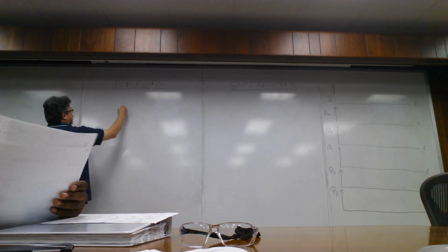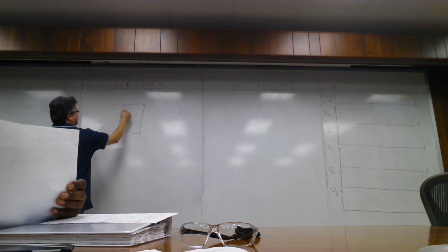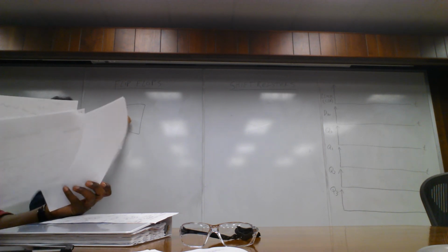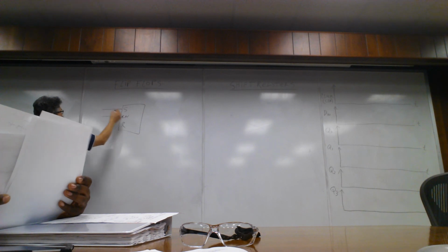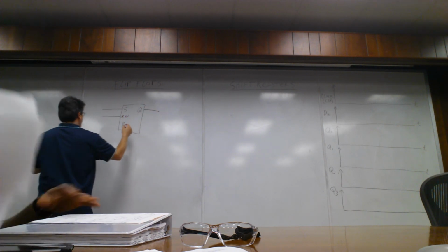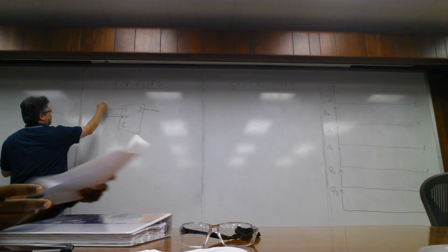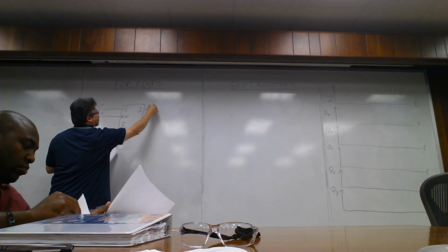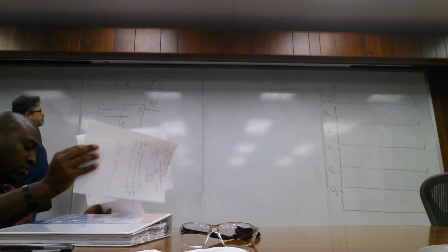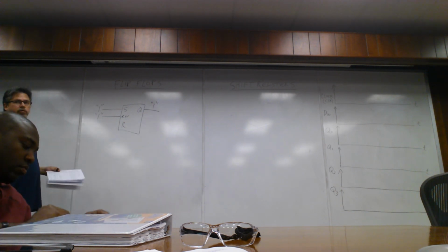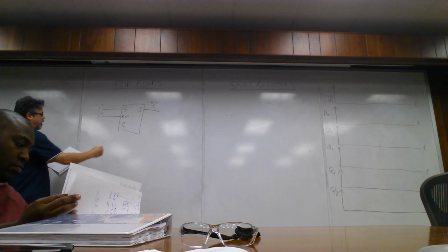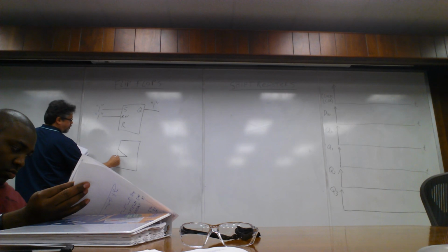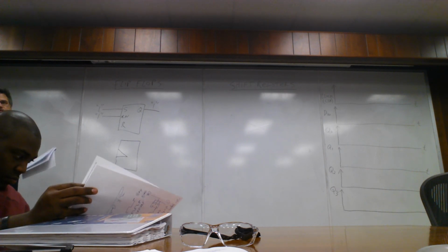So we talk about the basic latch. Latch, R, and we got enable. And that's obviously for a single bit. So if this is a 1 and enable is a 1, we set the Q bit. So we're storing a 1 in it. That's the typical latch.